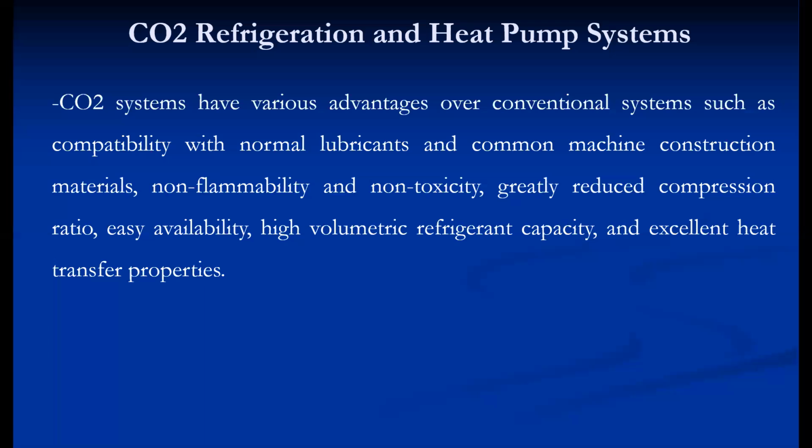And secondly, the environment crisis. Most of the gases used in refrigeration systems as refrigerants harm the environment. They increase the global warming potential, and they also deplete the ozone layer. To overcome this environment crisis, new refrigerants are coming up. CO2 is one of the refrigerants, an environment-friendly refrigerant, which has 0 ODP and 0 GWP. But there are some challenges in using CO2 as a refrigerant.